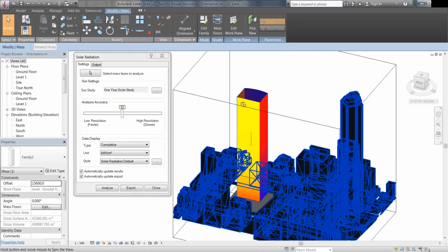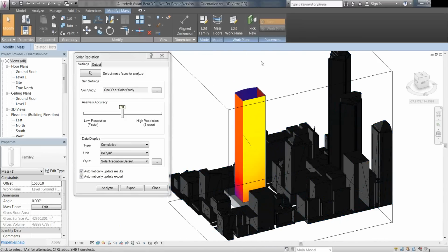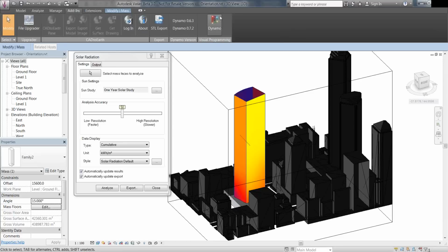So I've just created this. Again, heavy lifting is done in a Revit family. It's got a rotation parameter on it, so when I change the 10 to 10 degrees, it's going to rotate around by 10 and rerun the results there. So I could manually sit here and type in those numbers, but I want to analyze every single degree between 1 and 360. So let's look at a way to script that, and let's use Dynamo since it's so easy and awesome.